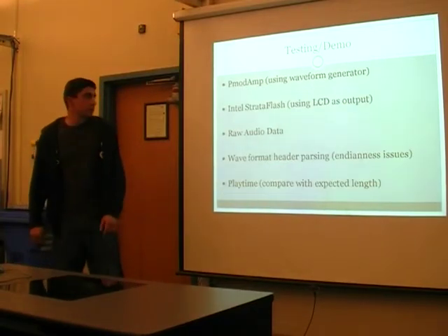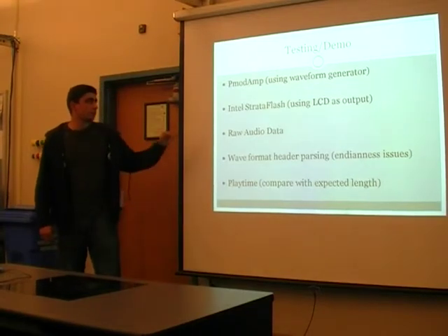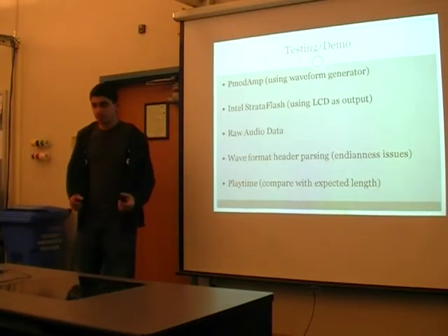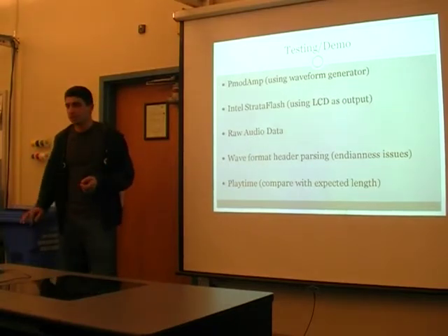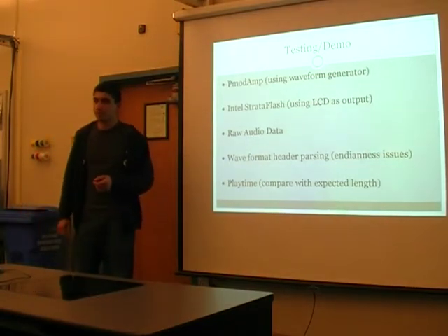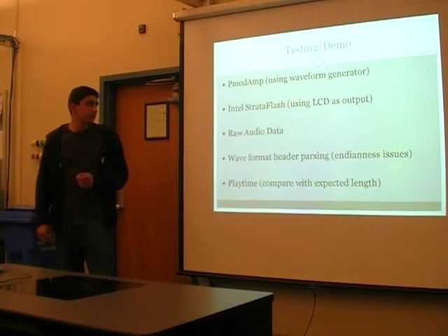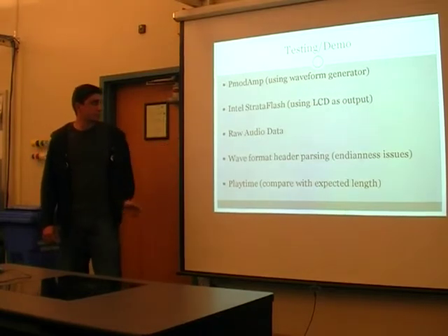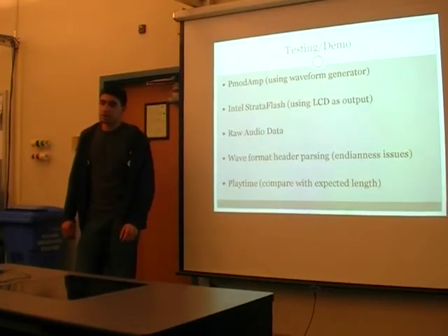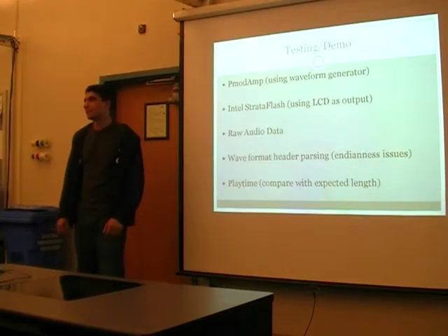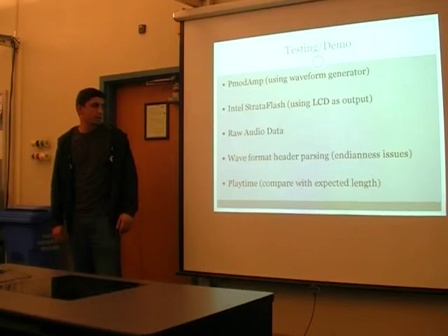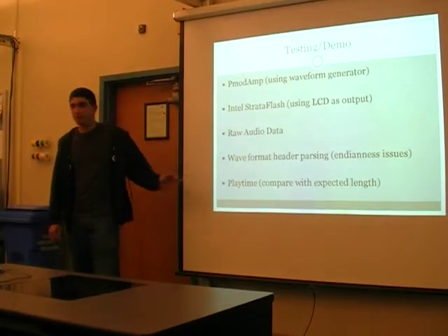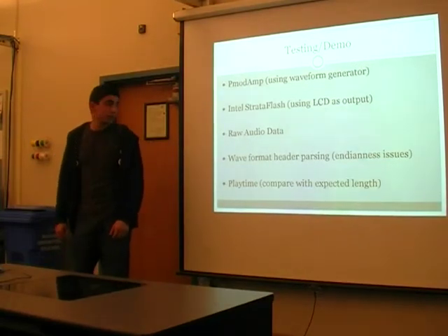To test the PMOD amplifier we were using, I just used a waveform generator and plugged into a speaker to make sure I could hear different tones at different frequencies. To test the flash memory, I initially flashed the alphabet, 26 bytes, then read it in and output it to the LCD to make sure I was reading the memory correctly.